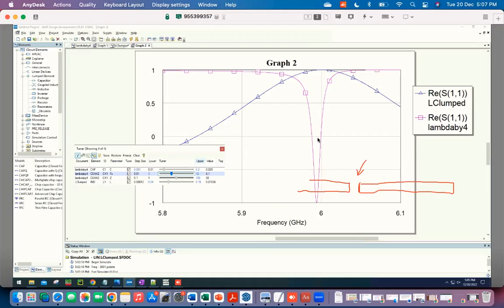If the width of these transmission lines is not big enough to give you a lot of capacitance, then you can do other kinds of tricks where you can have these kind of structures, integrated capacitors. You basically create more area, or you can even make an overlap capacitor by putting something connecting the two and having some dielectric, these overlapping. So you make a parallel plate capacitor if you need high capacitance, but that's usually not the case because you're always trying to make low capacitance. But this might happen under some circumstances.